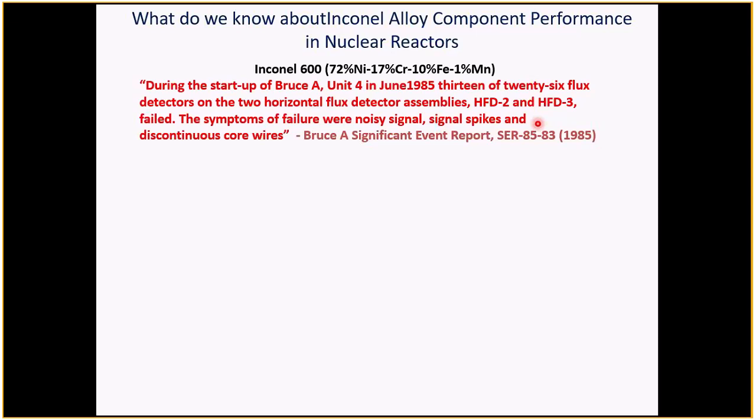If you have moist air, you can get reactions between the nitrogen in the air and the breakdown of the free radicals from the water in an ionizing environment, and actually get nitric acid, HNO3, and that attacks elements. Anyway, irrespective, it wasn't nitric acid, it wasn't stress corrosion cracking, it was something, because there was no stress.